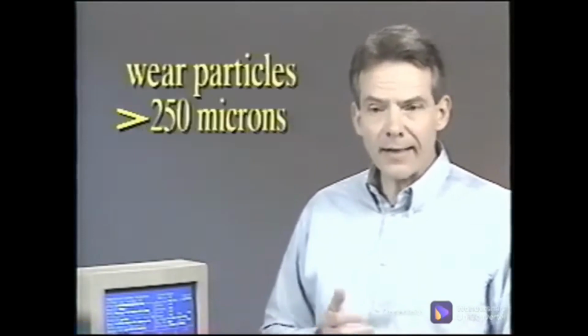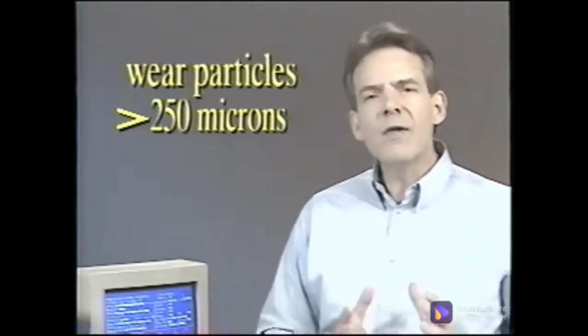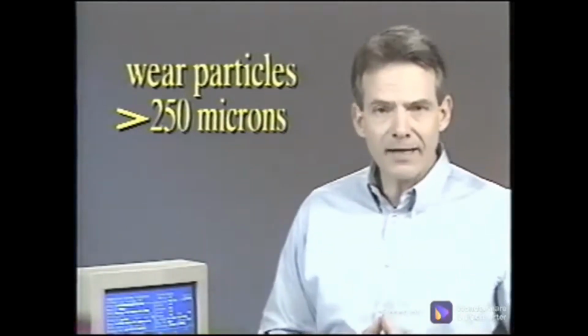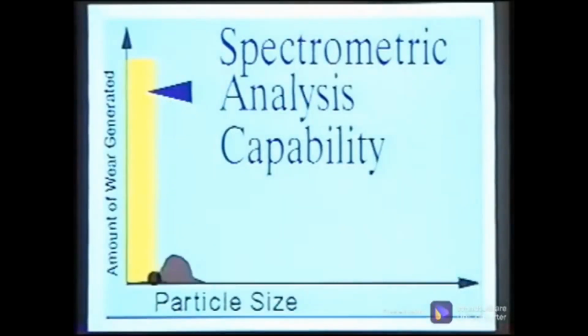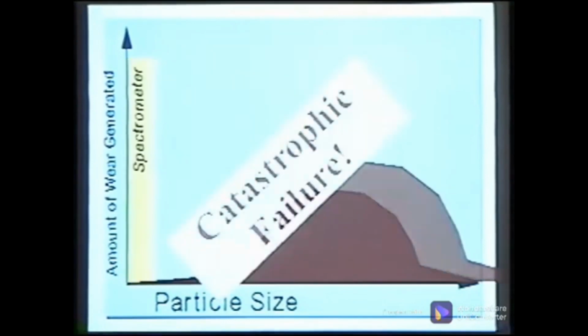When the sample was tested again for large wear particles, it had excessive ferrous fatigue wear chunks in excess of 250 microns. They were so large, they were ignored by the spectrometric oil analyzer. A failure progression typically begins with wear particles in the 10 to 20 micron range, increasing in size and number until failure. Wear particles in the final stages can be in excess of hundreds of microns. Wear particles give the best indication of the severity, but may be overlooked with spectrometric oil analysis.